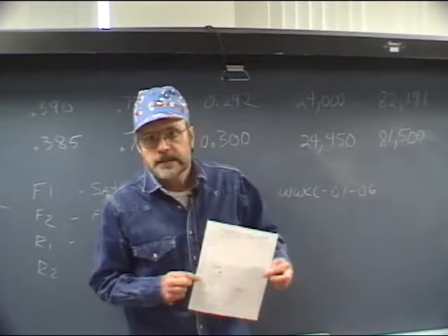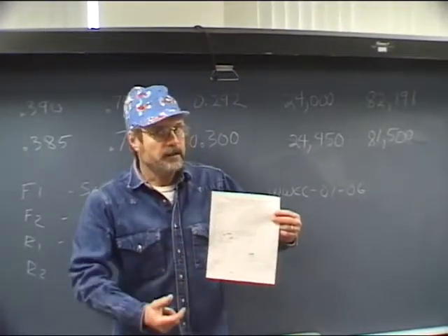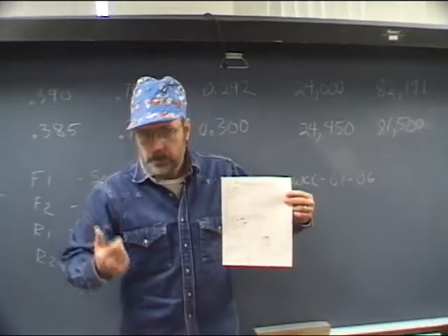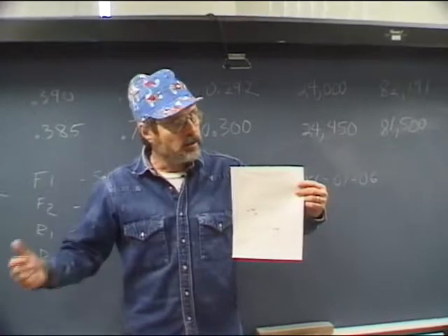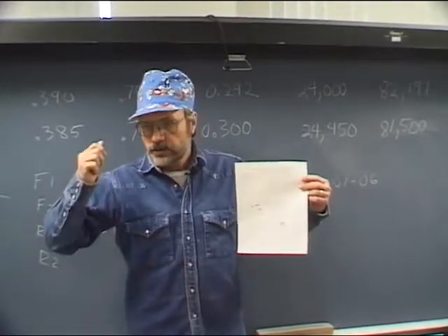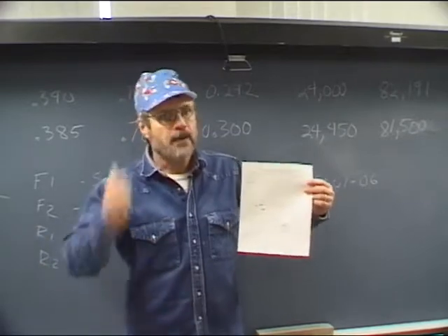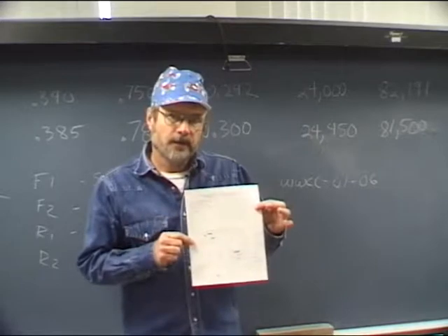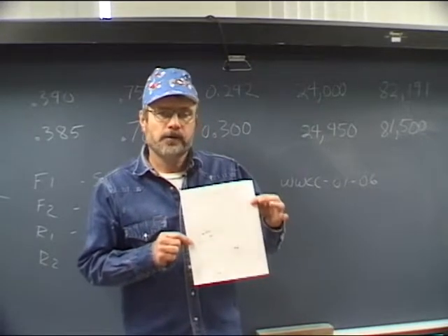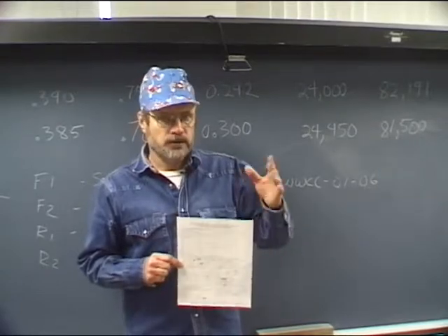So that then takes us through this first form. And remember, the first form, you're sitting there with your little micrometer and your meter gauge, and you're recording all the actual values. You've got your pyrometer, your temp sticks, everything, your tape measure, your stopwatch to get the inches per minute, and all that information goes into the PQR. Okay? Actual values have to be recorded in the PQR. The PQR backs up the welding procedure, which is our next document.